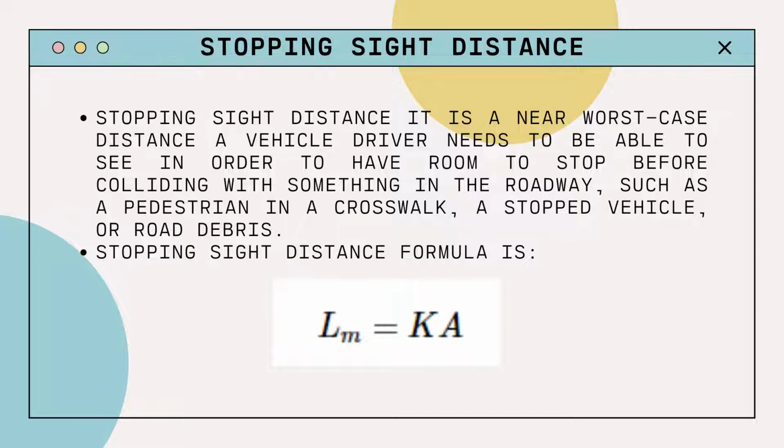Sight distance is dependent on the type of curve used and the site speed. For crest curves, the sight distance is limited by the curve itself, as the curve is the obstruction. For sag curves, sight distance is generally only limited by headlight range.